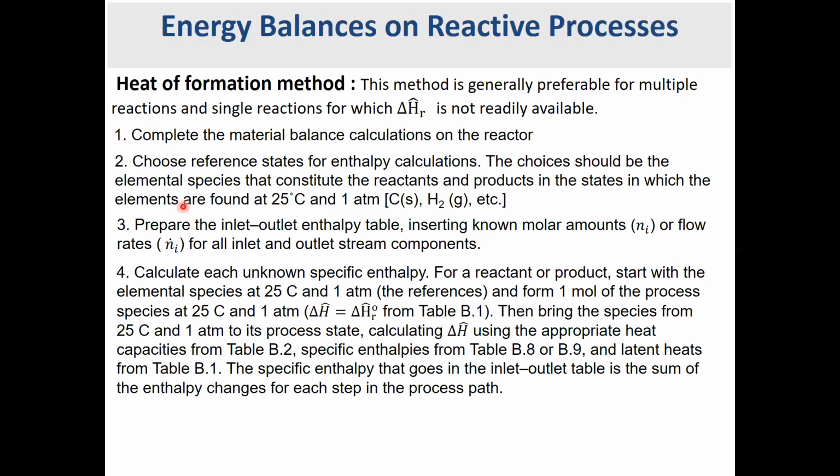This heat of formation is when the specified elements react together and form that specific component. So in table B1, you can read the standard heat of formation at 25 degrees and 1 atmosphere. However, if the component in your reaction has other temperature and pressure, you have to do further calculation to calculate those values. So you may use table B2, you may use table B8 or B9 in this way. We will explain how. At the end, you just put in the simple equation that we have so far and calculate